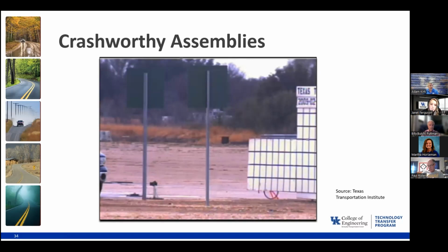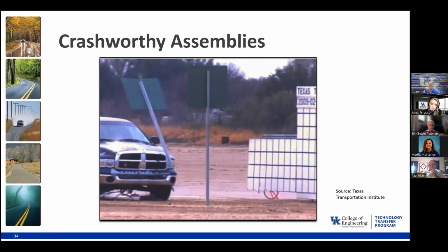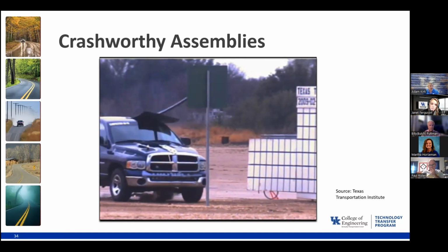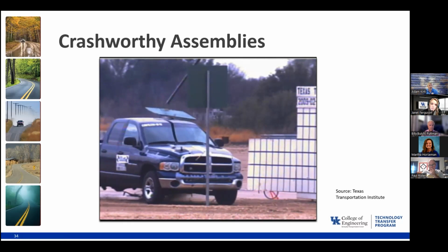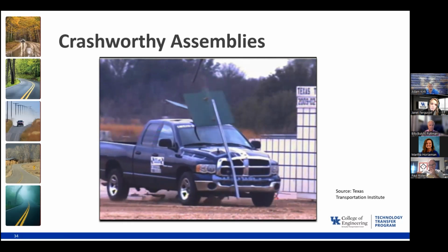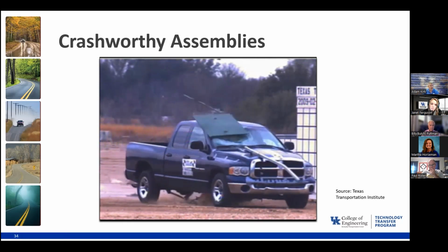And then we're going to see another one that is actually a higher tensile strength than's recommended. And we'll see how that differs in its performance when you don't meet those specifications that we've got. So it's kind of in slow motion, but you can see this truck's coming through. He's going to hit this first post. You can see that snaps, breaks away, and goes directly over the vehicle. And then hit this next one, and it performs differently.